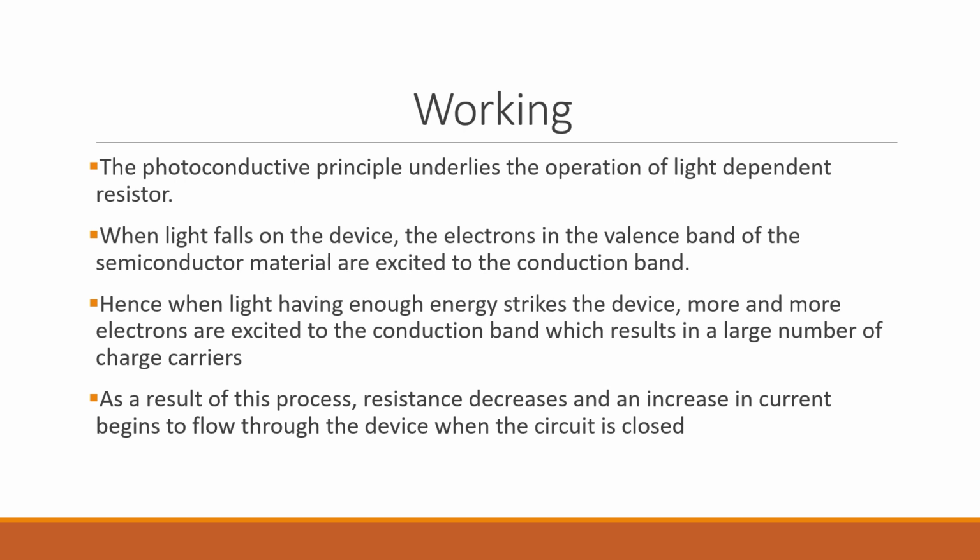So basically it works on the principle of photoconductivity. Photoconductivity is an optical phenomenon in which the material conductivity is increased when light is absorbed by the material. When light, or we can say a photon, falls on the device, the electrons in the valence band of the semiconductor are excited to the conduction band. The photons in the incident light should have greater energy than the band gap of the semiconductor to make the electrons jump from the valence band to the conduction band.